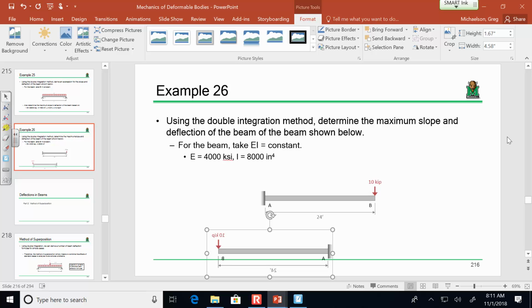The reason why I do that is because when in doubt, when you're doing beam deflection calcs, and this is true if you're trying to define moment functions or anything like that, generally what is easier from an algebra standpoint is to define your origin where your free end is. So if you put the origin here and say this is the x-axis and this is the y-axis, you will generally make your life easier from an algebra standpoint, guaranteed. Okay? So the reason why I mention that and why I do that with this problem is because the way that this problem is